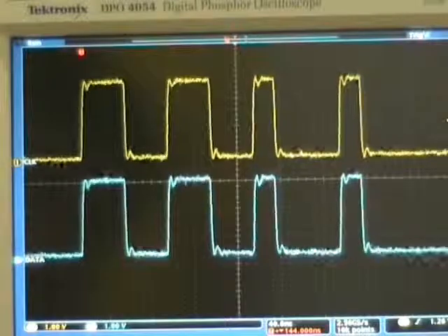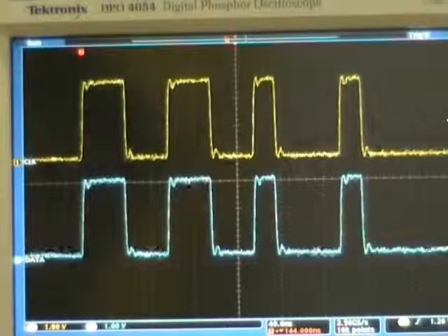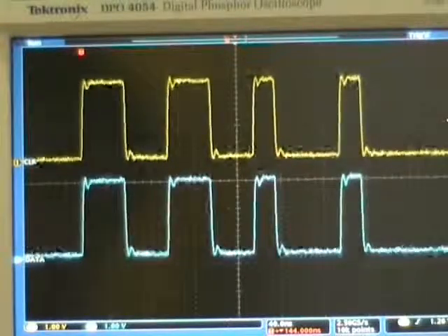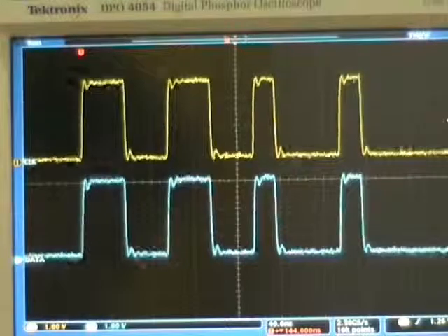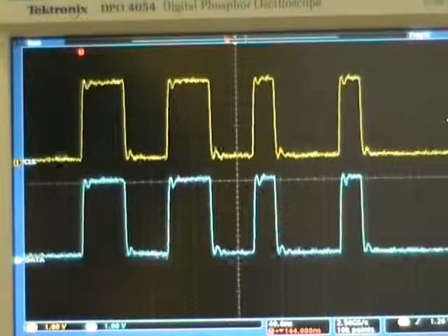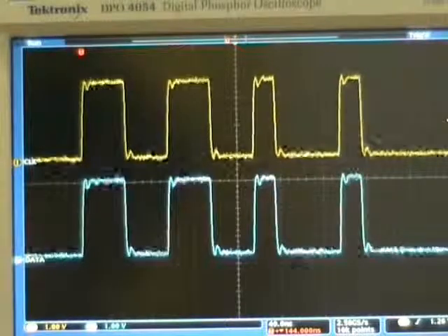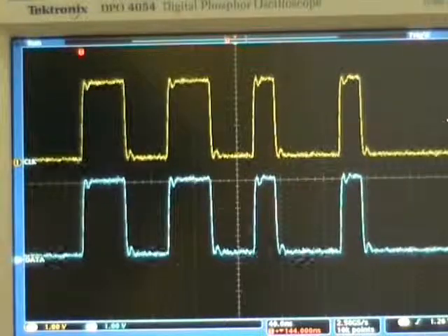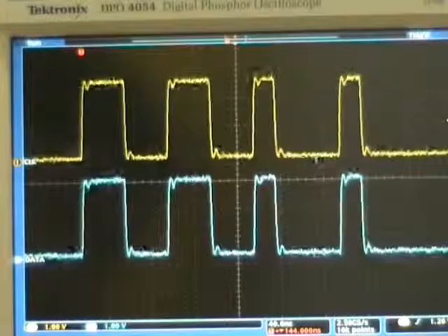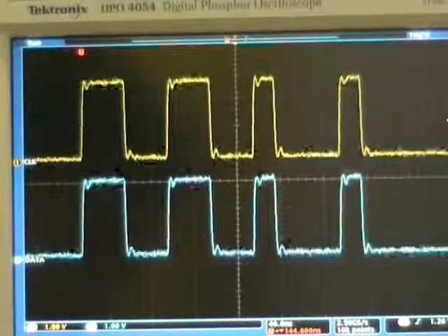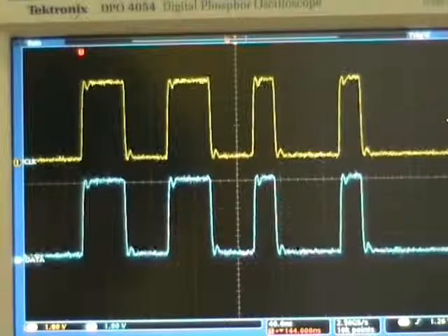And on the right portion of the yellow curve, we can see data 1010 as well. However, because the time set we use is RZ, meaning return to 0, the data 1 must return to 0 before the cycle ends. In fact, if you remember, based on our configuration in the software, it actually returns to 0 at the edge position of 25 nanoseconds.